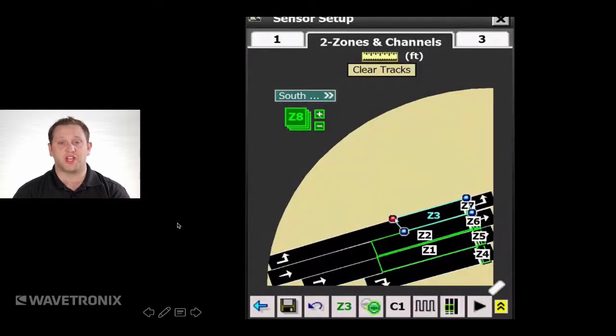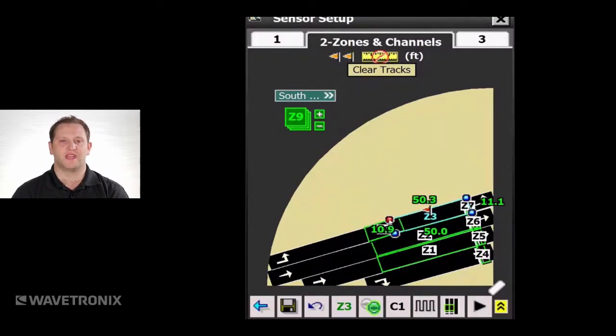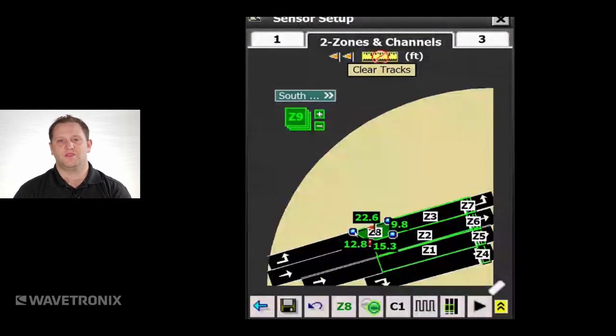You can adjust them. It is permanent once you set it, but if you wanted to make a change to the zones, you could make a quick change to the zones. Oh, I want to move that forward a little bit, move that back a little bit, based on the traffic flow. And so here, I'm looking at the range, and I said, oh, it's only 44 feet, and I really wanted it 50 feet. So I can kind of grab those little nodes there, and I can move them back a little bit, and then I can move that other zone a little bit as well, just to make sure that it's going to detect the third car back, and we'll get that. And with that delay, that's going to make that intersection run pretty snappy.